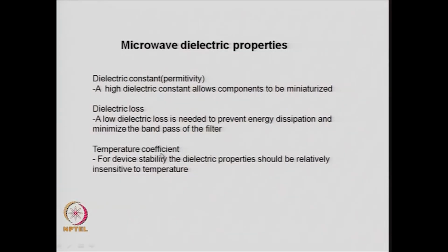So, at a particular frequency, if you check the dielectric constant and then change the temperature and again check the dielectric constant at the same frequency, the two should be nearly equal. If it has changed a lot, then you cannot use them in many applications. You need a temperature coefficient which is as close to 0 as possible, especially for materials which show microwave dielectric properties.